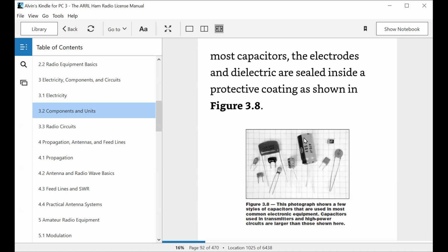The capacitor will try to steal electricity from the ohm meter to build up a charge. So what you'll see in the meter is that you'll first find almost 0 ohms. It'll dip down real fast, and then later on you'll see the meter sort of build up to a high resistance, and that's normal. I'm only mentioning it because that's one of the questions on the exam.